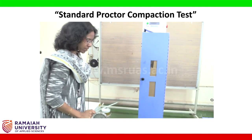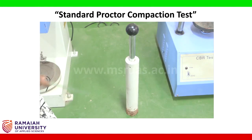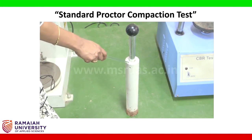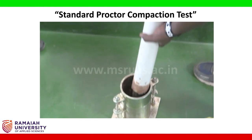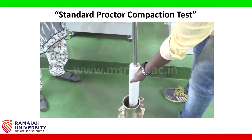For light compaction, in this case, we are going to use the rammer whose weight is 2.6 kg and the height of fall is 310 mm. Place the rammer on the top of the soil layer, raise it to 310 mm and leave it.